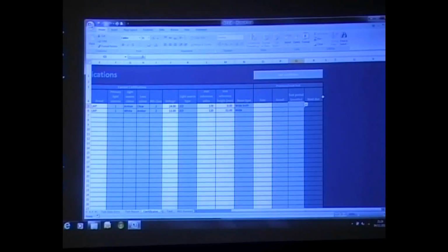Sorry, Rick, you were going to say something. No, just coming back to the LED floodlights, sort of similar. A lot of them, certainly through eBay, but even through Amazon, have come from Hong Kong. I've had several and immediately raised a complaint, not earthed. CE marking on them, metal box, metal casing, and inside there's an earth lead, and there's a ring tag on the end. And it's just floating loose because there's nowhere to fasten it to.